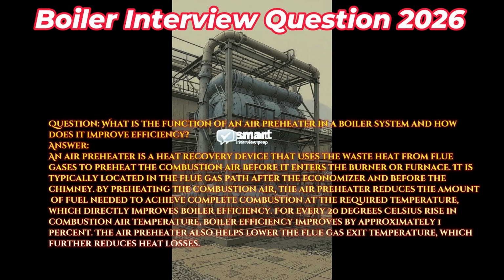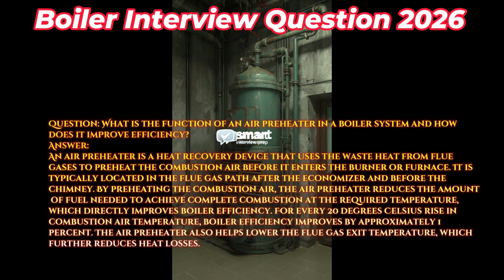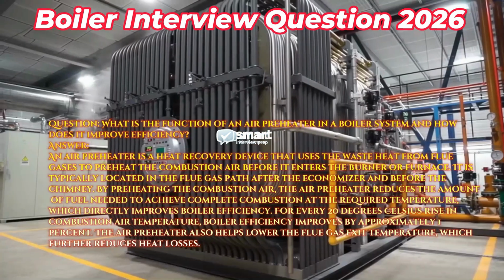Question: what is the function of an air preheater in a boiler system and how does it improve efficiency? Answer: an air preheater is a heat recovery device that uses the waste heat from flue gases to preheat the combustion air before it enters the burner or furnace. It is typically located in the flue gas path after the economizer and before the chimney.